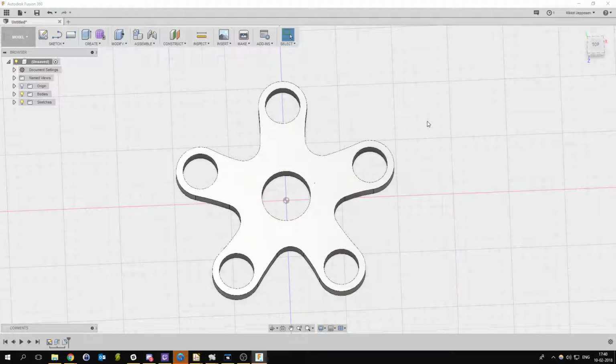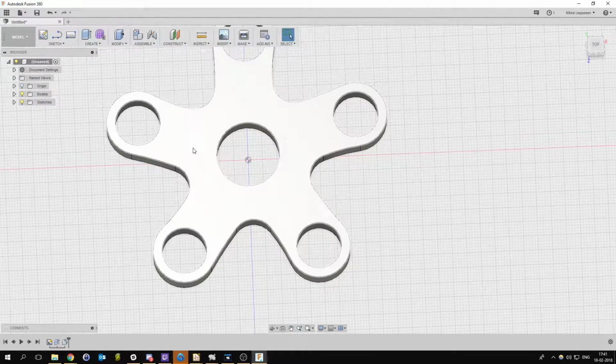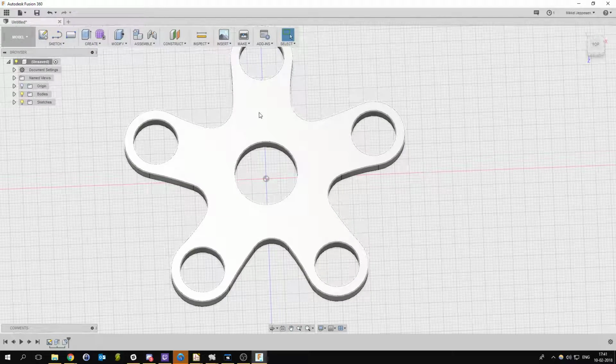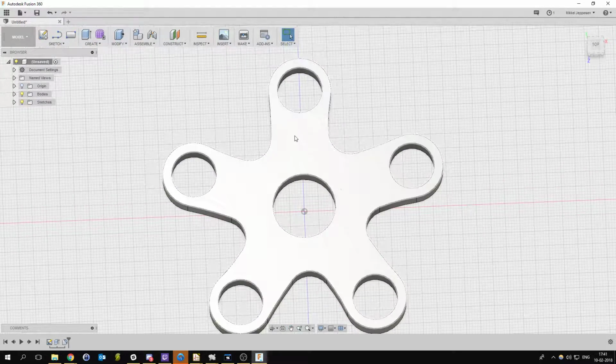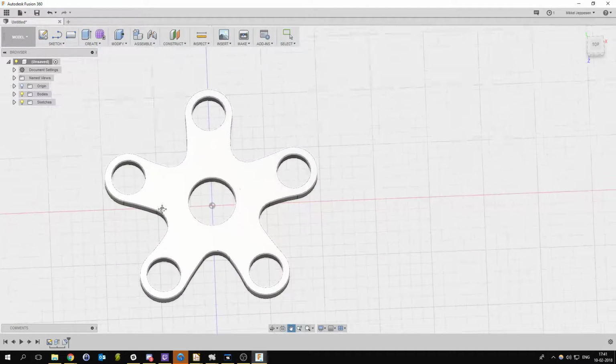Yeah, I think I know what you mean with clicking the body call code. I usually don't do that in Onshape either. Basically what it does in Onshape, I'm assuming it does the same thing here. It just picks every outline on that face. So if I click this face up here for a fillet or a chamfer, it would pick the outline circle and the inner circles, all the other circles. I usually don't want to do that because there's usually 1 or 2 things I don't want to fillet or chamfer. So usually I just pick the lines myself. But yeah, it's definitely an option.